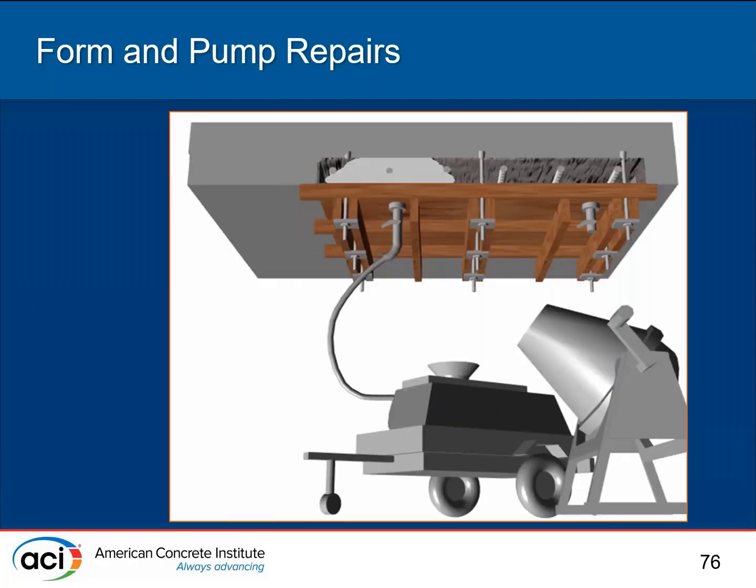Form and pump is a little bit different in that instead of just pouring it in and working its way under gravity and then with some vibration, the new repair material is injected or put into the cavity under pressure. The advantage of this is it helps get the repair material into intimate contact with the existing concrete, so it works on the bond, and it helps it get into places it wouldn't otherwise go.